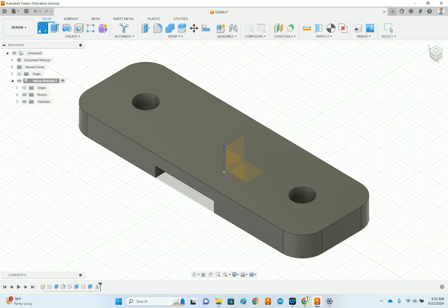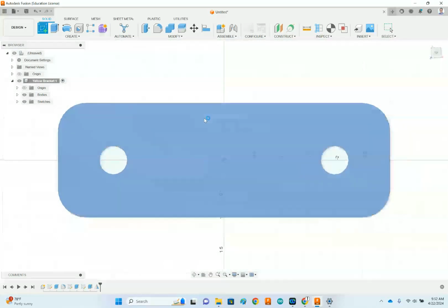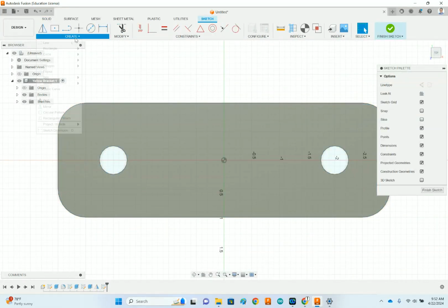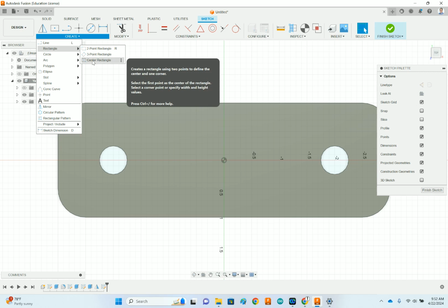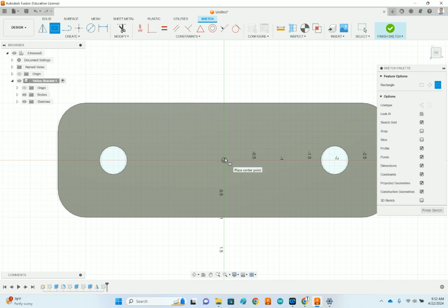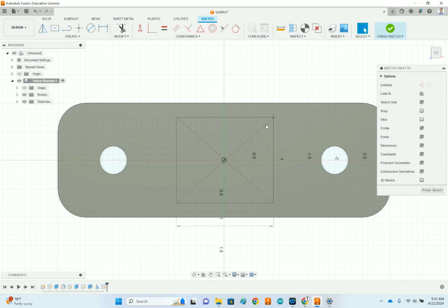Let's create a sketch on this top surface. It's going to be a center rectangle with its center right there. Okay. It's going to be 1.75 wide, tab, 1.5 tall. Enter. Now, if you didn't do the tab, if you hit enter by accident, in other words, if these numbers you didn't put in when you did it, I'm just going to delete them now